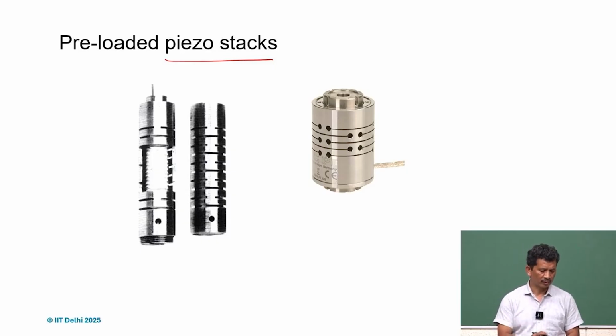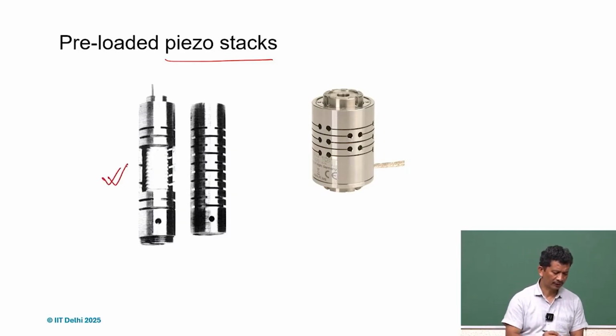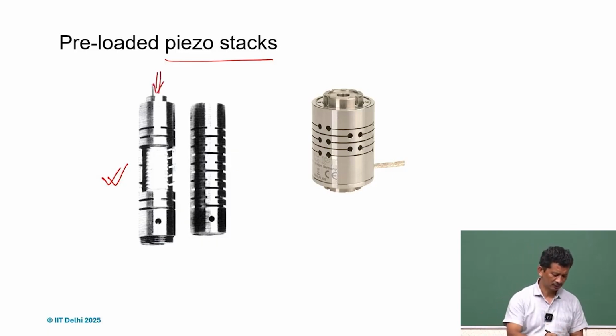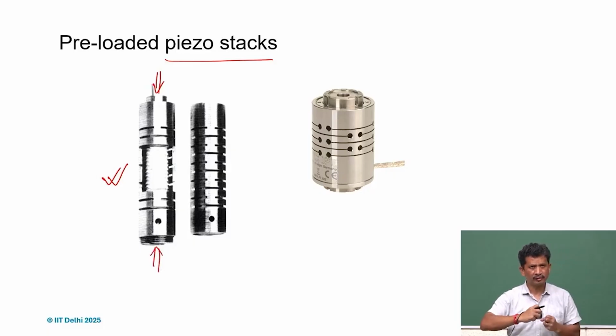So we can use this kind of arrangement, with alternate cuts, and H is chosen in such a way that when we tighten it from the ends, we can compress the tube and the tube gets extended, and the material gets compressed inside. That is a very useful method in designing these kinds of actuators.